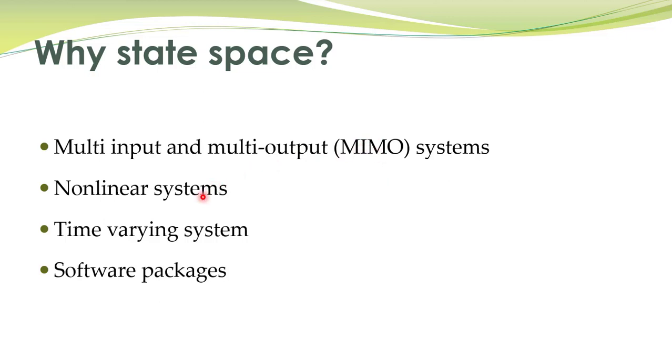Another advantage of state space analysis and design is that nonlinear systems can be easily described by state equations. You remember that transfer functions are only for linear systems. We cannot write a transfer function of a nonlinear system. However, this state space representation is equally applicable to nonlinear systems as well. Furthermore, time varying systems can be handled with this approach, and one of the major advantages is that these techniques are favorable to modern computers. Therefore these are extensively studied.